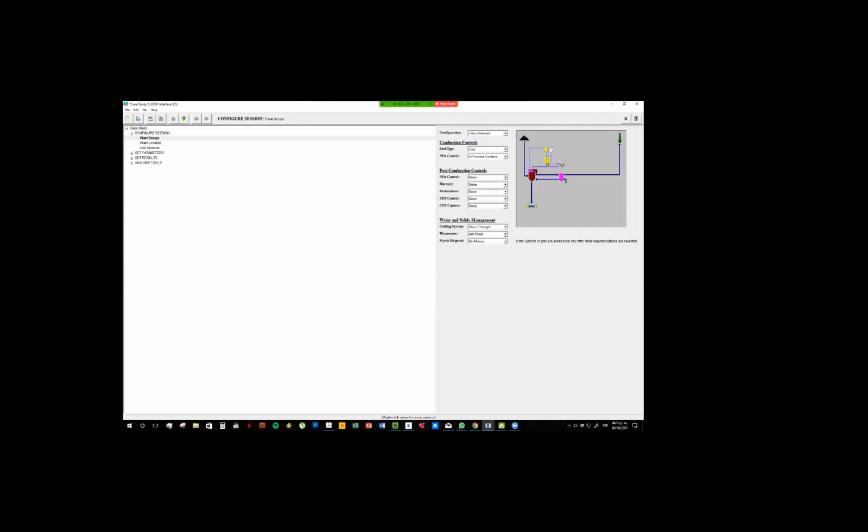But many times that's not an option. So we have, for example, a cooling tower. That's more efficient, ecologically speaking. But if you have a river and you're not going to change too much the temperature of that particular water, you can return it. Then you have the air-cooled condenser, that, as the name implies, uses air to cool the water, well, to cool the stream and to condense the water.